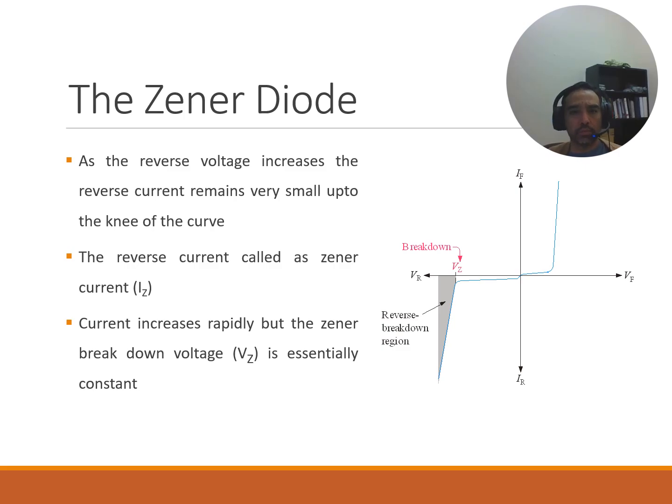The first one we said was what? Avalanche breakdown. A step up explanation would be, within the avalanche breakdown, this happens when the reverse voltage is really high. So again, going back a little bit to the last explanation, imagine water trying to break through a dam, right? If it gets too strong, the dam, or in this case, the diode, will let the water pass, but in a controlled way. So this can happen in both a regular and a Zener diode at high voltages, right? And then there was the other thing we talked about, which was the Zener breakdown.